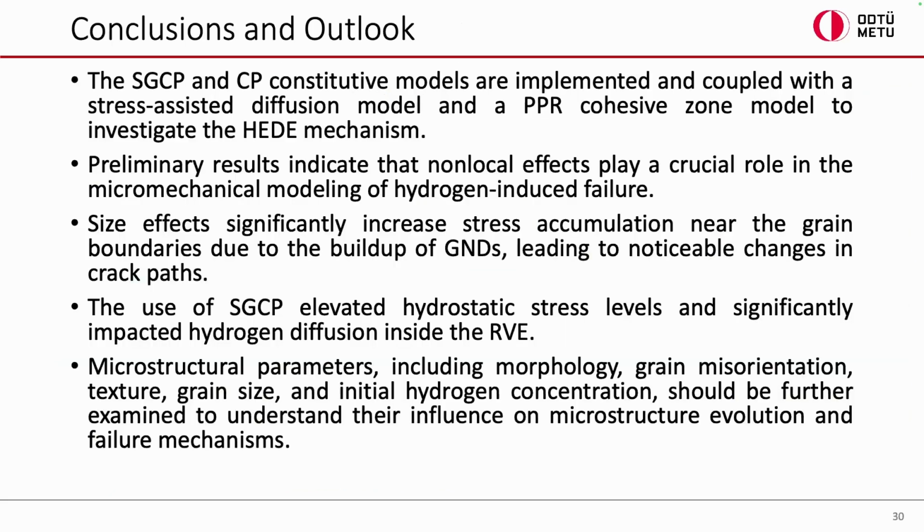To give my conclusions and outlook, we implemented the strain gradient crystal plasticity models to deduce some results based on the hydrogen enhanced decohesion mechanism, and to check the effect of non-locality on stress concentration, hydrogen concentration, and hydrostatic stress accumulation.